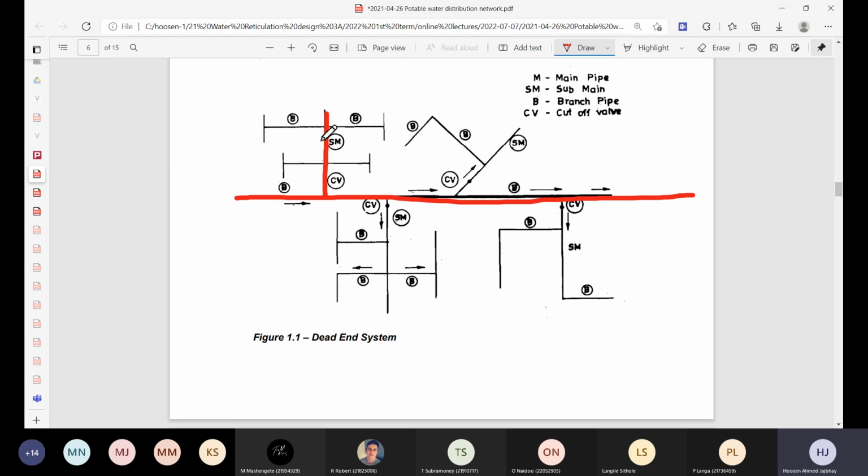And if it's a sub-main pipe, so it's still some sort of a main, so it's going to supply water to other pipes. And then you have your branches from that. So now it's the branches that are actually going through your streets and roads and whatever, and that are supplying the houses from there. Right. So you're going to have the branches from there. And then from that, you then have your house connections, whatever, and you then connect up from there wherever the properties are, or wherever the industries or schools or hospitals are.